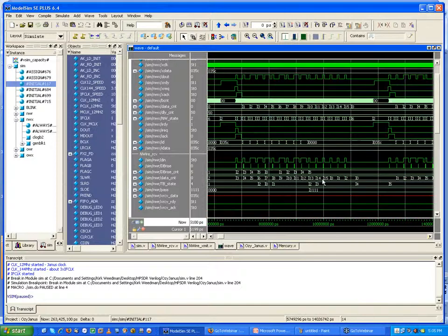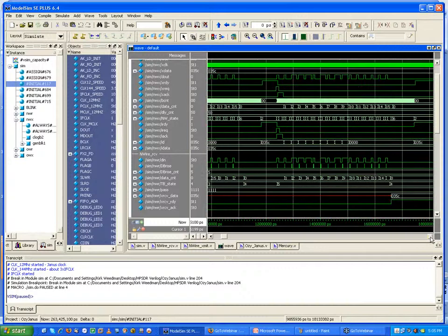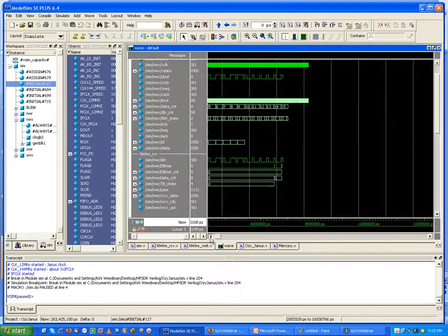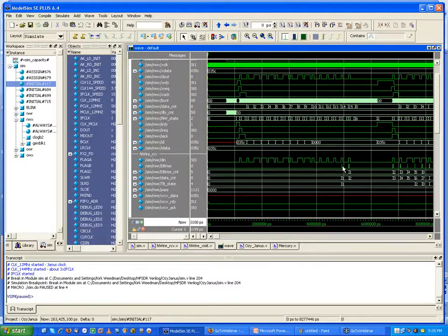And then on the next, not on this second cycle, but on the actual third one, it's got it figured out and it's latched the data in now. So it's working properly at this point. So that was one of my main requirements in eliminating the sync bits. I had to still figure it out and make sure that no matter where I hit this data stream, say Mercury comes up, or I reprogram it, because I didn't want to have to reprogram the FPGA. I just want to be able to download it through the ByteBlaster because it's much quicker that way while I'm debugging.